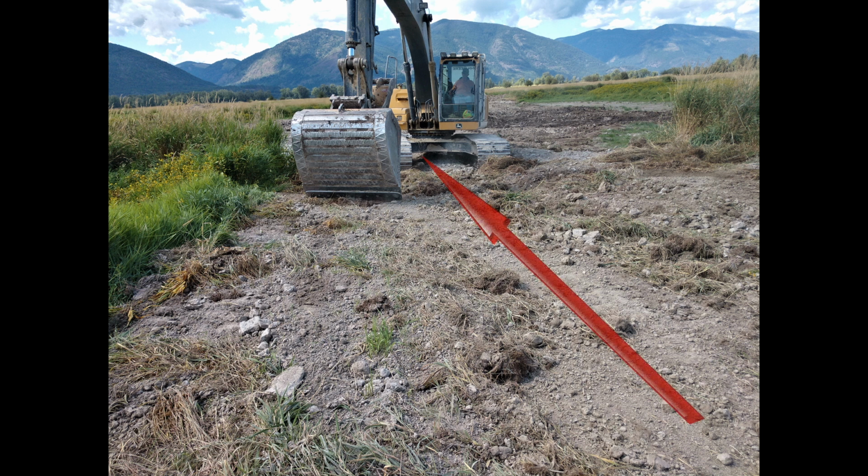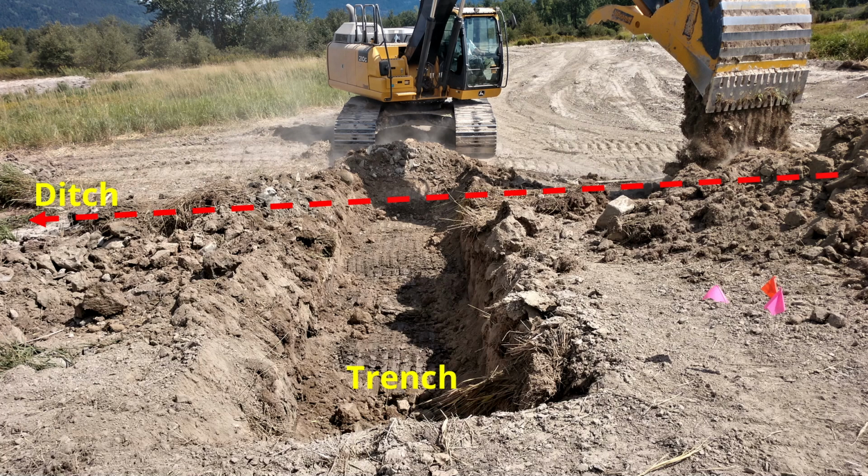The ditch is shown by the red arrow. The purpose of the groundwater dam is to control the water in the soil beneath the ditch and the flow of water in the ditch. The groundwater dam is built where the natural rim of the historic wetland was located. The pink wire flags show the operator where to begin and end digging the trench for the groundwater dam. The trench is being dug about 5 feet wide.